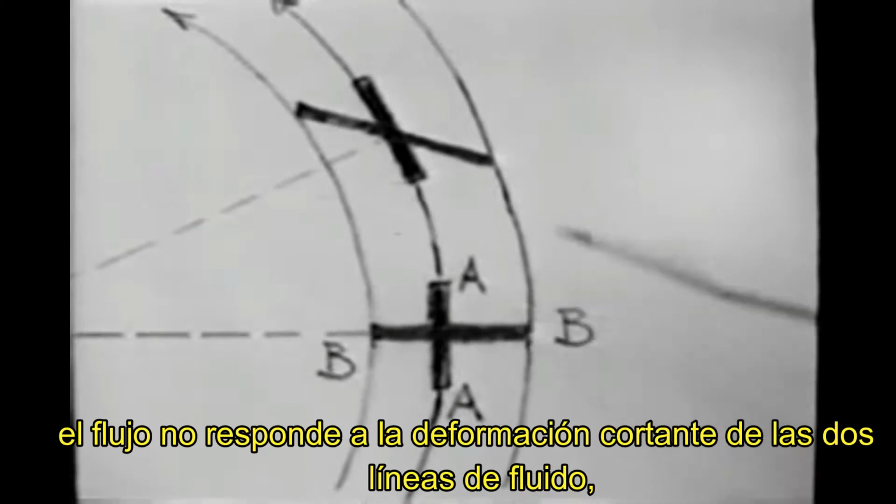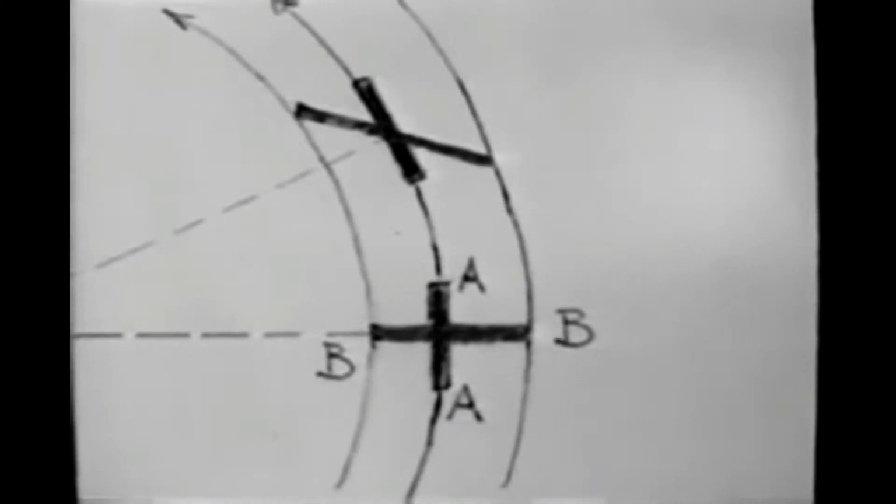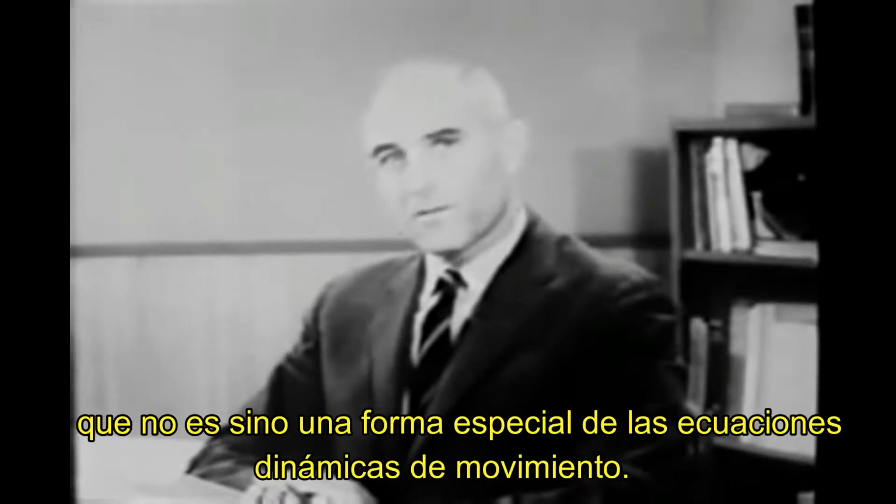Incidentally, since the two vanes of the float are rigidly connected, the float does not respond to the shear deformation of the two fluid lines, but only to their average angular velocity. There are several theorems which relate the vorticity to the dynamics of fluid flow. One of these is Crocco's theorem, which is nothing but a special form of the dynamical equations of motion.